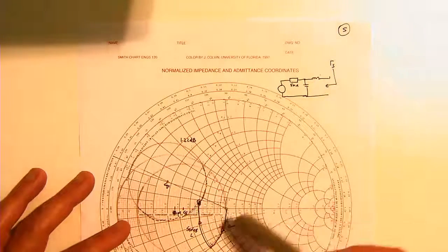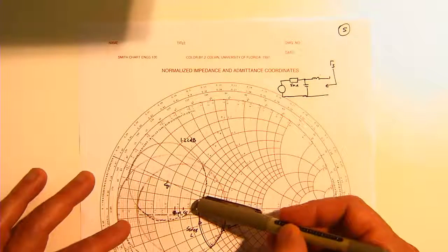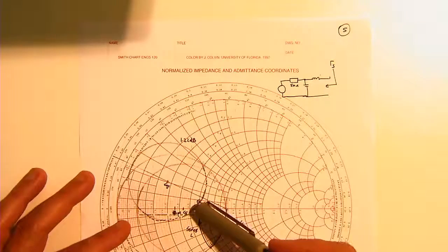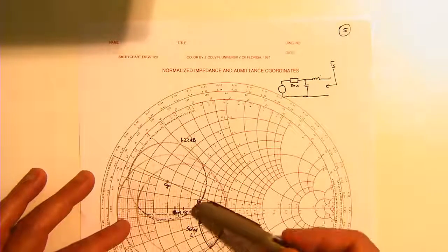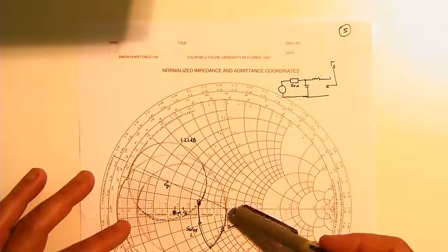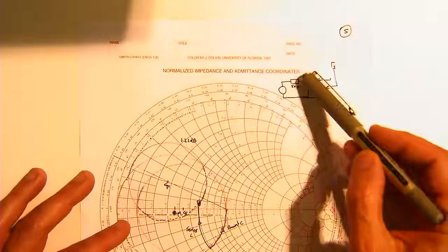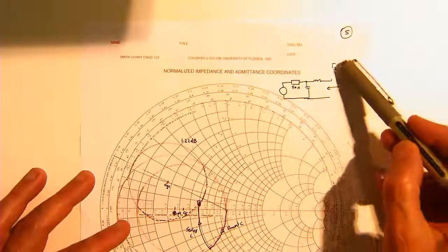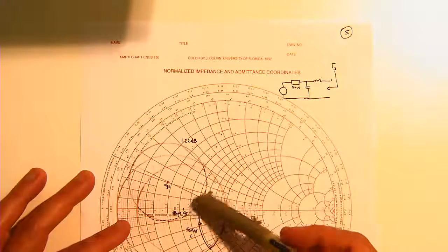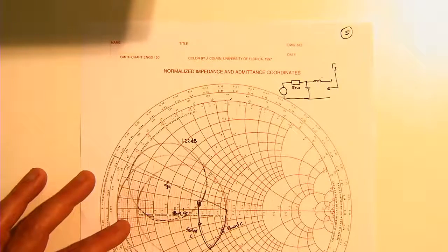And then what we went through the process was this, we arbitrarily, right? So this is an important point. We arbitrarily chose a point on this gain circle. I chose that point so that it gave us the lowest voltage standing wave ratio, and then we went through the process of working out what was the network that would allow us to transform the 50 ohm generator source into the impedance that I require in order to achieve the source impedance that allows me to achieve both the noise figure and the specified gain.